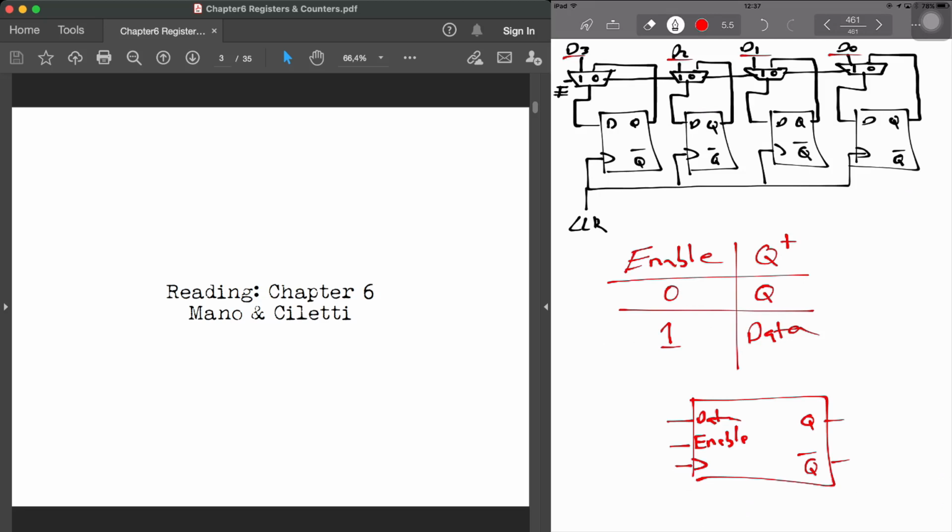By the way, if you have any questions, please note them down, and while we are having the live sessions, you can ask me those questions. So a 4-bit register with parallel load is demonstrated. It's actually a single bit over here, but that can be represented as 4 bits with 4 D-type flip-flops as shown over here. So we can just use a symbol if you want to implement a 4-bit one after the other, and we can just put that down.